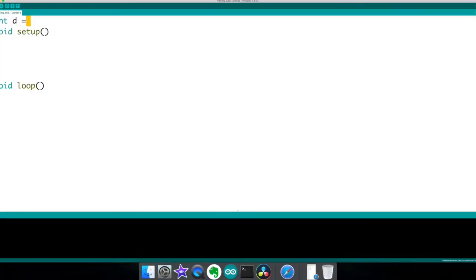So what we're going to do now is make a variable called wait, and make that equal to 5. So wait is going to be our delay time, and we're going to make that 5 milliseconds, so it's extremely short. Over here we're going to write pinMode. Since it is connected to pin 3 as our PWM pin, we write 3, and then OUTPUT.